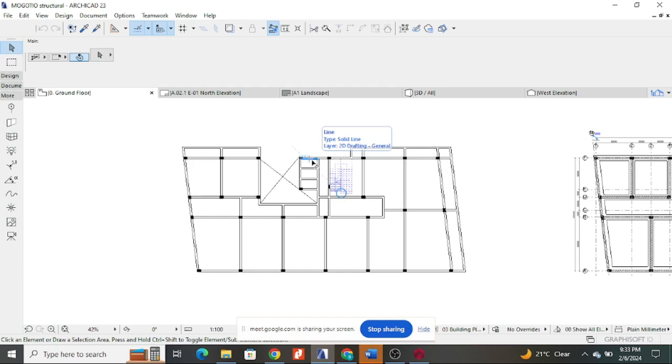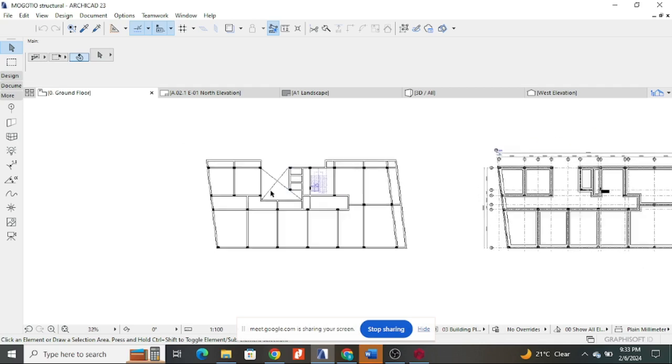And then you go to the first floor, you find out, do I have any other wall that is going to load my slab in a way that it will need a beam? You either add the beam or you design the slab to carry that wall.